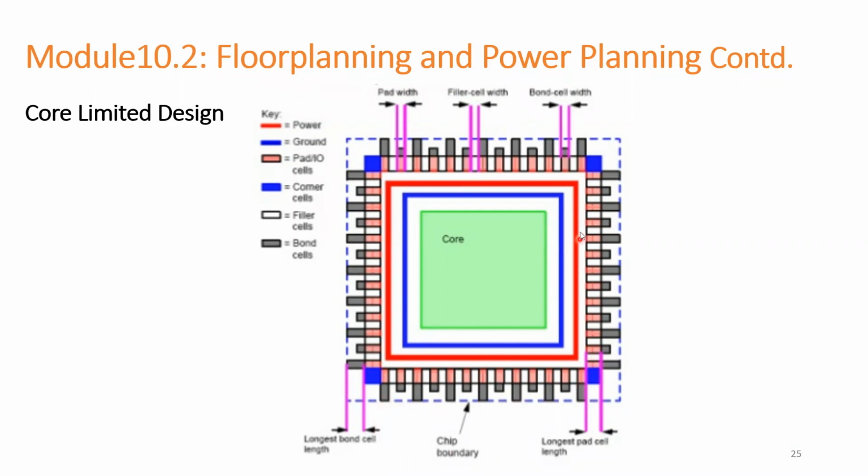This is the chip boundary. If there are any bumps, these will act as signal ports and power ground ports at top level. Those bumps will sit and be placed in the middle, or they can be placed in the corners for signal and clock routes.